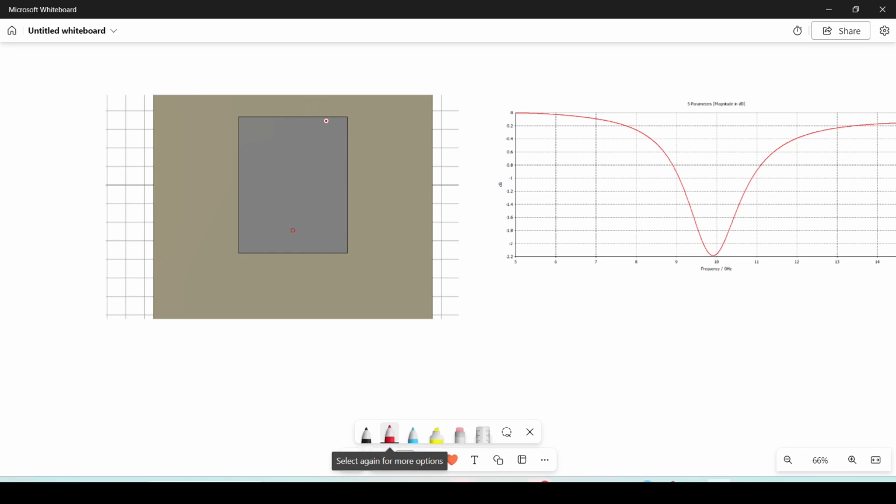Okay, so we know well that the patch radiates like this, right? If we look at the cross section, here we have two opposite things. It means that they cancel each other. And then if we look at the E pattern, it will be something like this: maximum, 0, maximum from the other side, like positive maximum, 0, negative maximum.